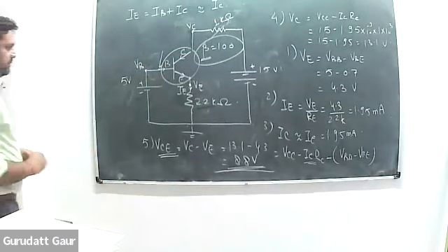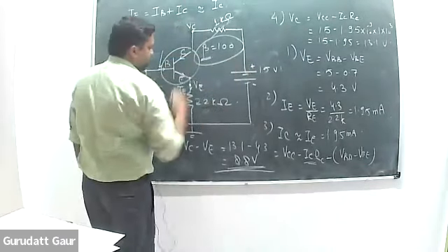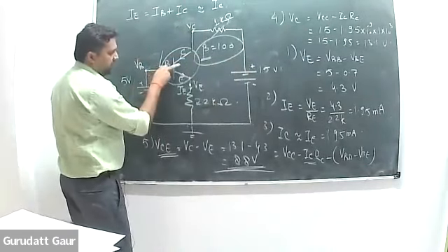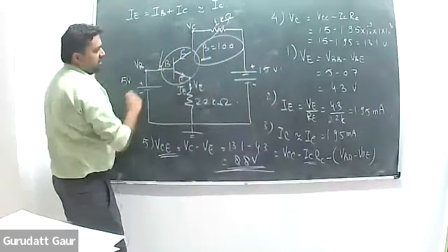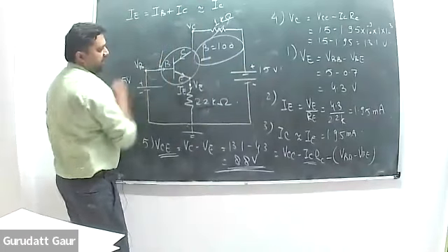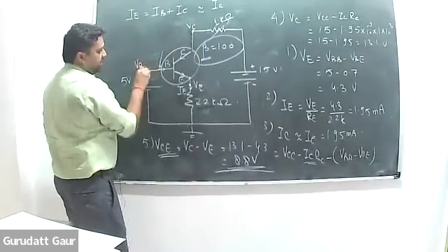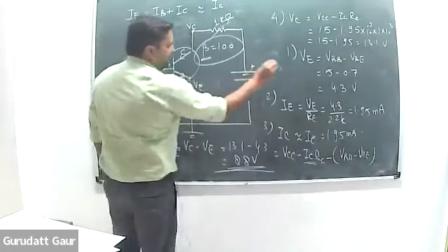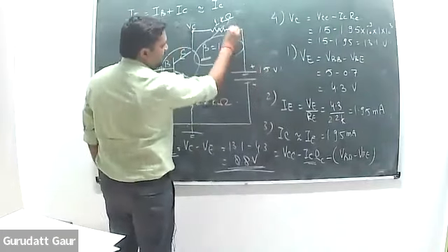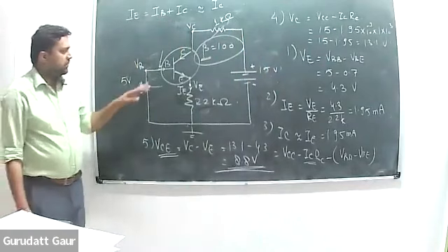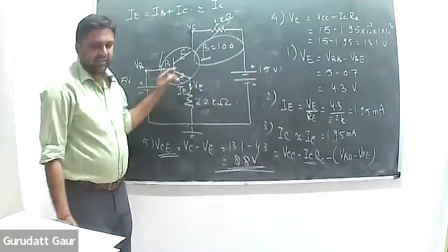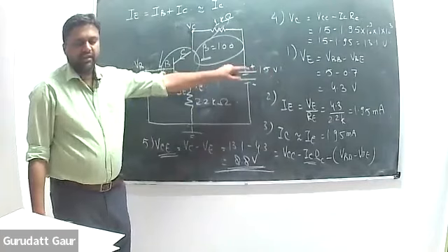But if you put another transistor here back to back, so now this will give you 180-degree phase, and then another will give you 180-degree phase. So finally you will get in phase. So output here and input here, they will be in phase. But input here and the output there, they still will be at 180-degree phase. So that's why one of the input terminal is known as the non-inverting. Another one is known as the inverting terminal.